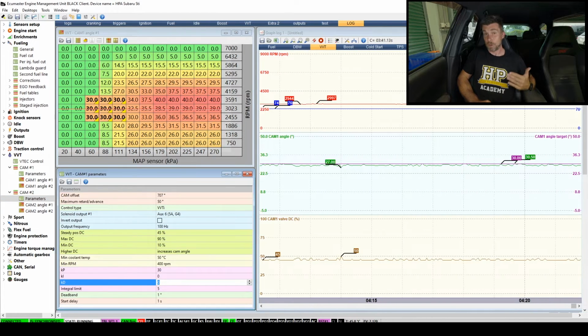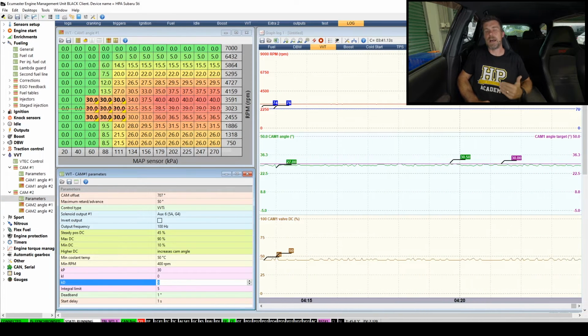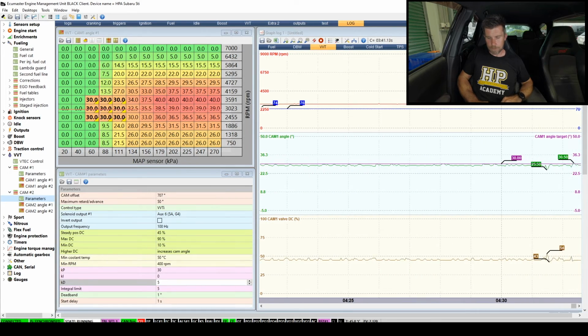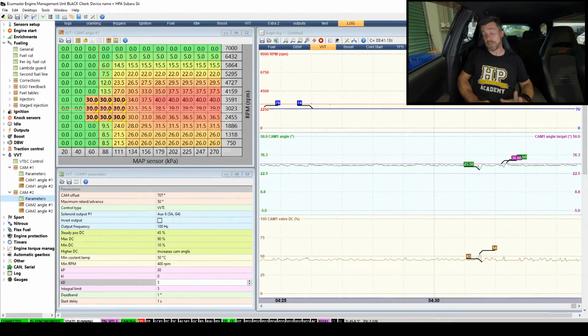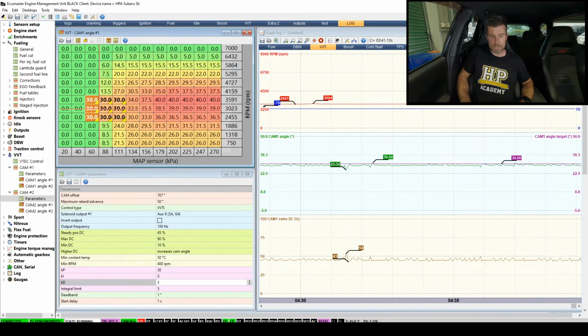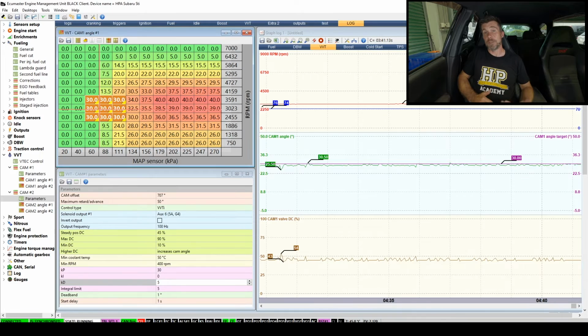We're going to actually move out of order here. We'll skip our integral component and we're going to come back to that. We'll actually work on our derivative now. So let's start by adding a derivative component of 5 here. On its own right now that's not going to show us any result whatsoever. Remember that works in the respect of the rate of change of error.